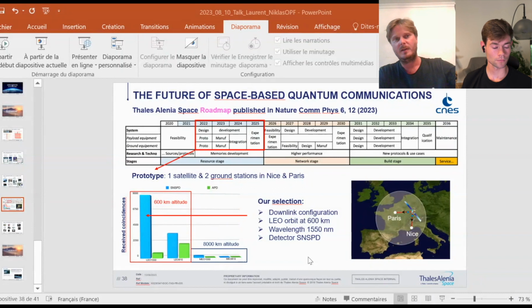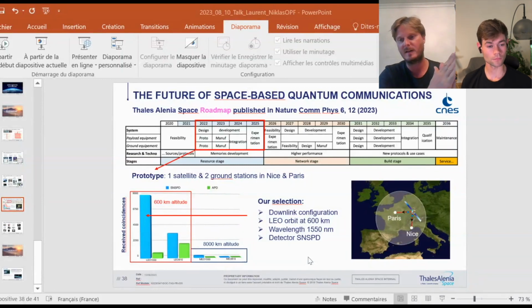And in fact, this compensation is better in a downlink than in uplink, because in uplink, to compensate these impairments, you need a beam coming from the satellite to the ground, and when you use this beam to correct an uplink beam, the problem is that the satellite has moved.